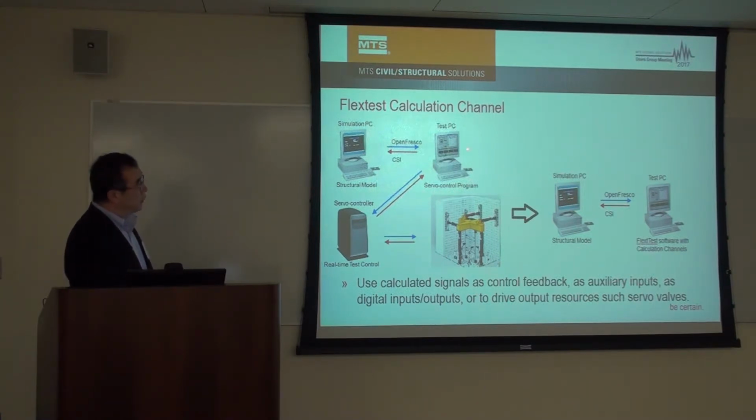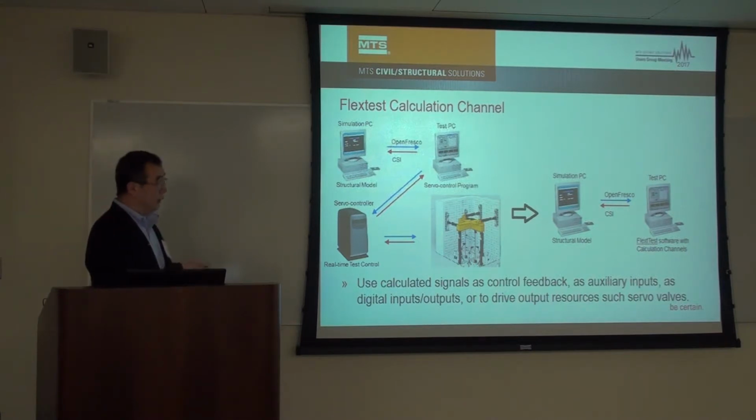We build a virtual station inside this controller, and then the OpenSees model sends commands through OpenFresco to this virtual station. This virtual station is built by calculation channel. Later on, I will talk in detail.